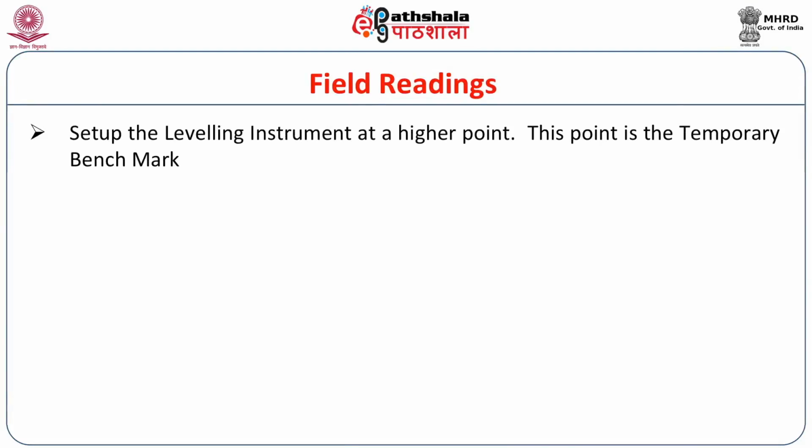One of the factors that helps us in fixing the instrument is that, whatever area we select to do the survey, we have to see that the instrument is set up usually at the highest point of the survey area, or otherwise if the survey area is not very large, then even nearby the highest point of the survey area. And usually the center of the instrument, we call it the temporary benchmark.